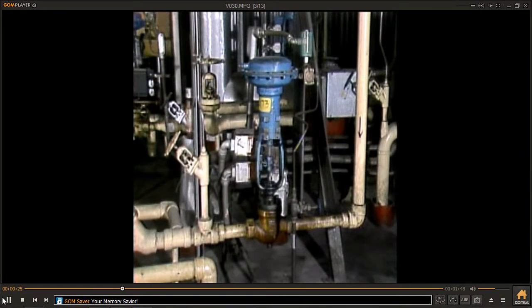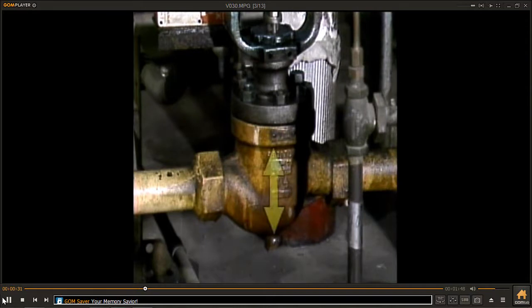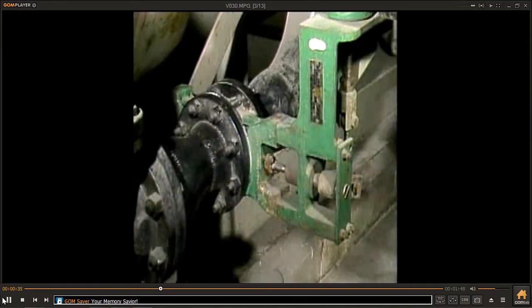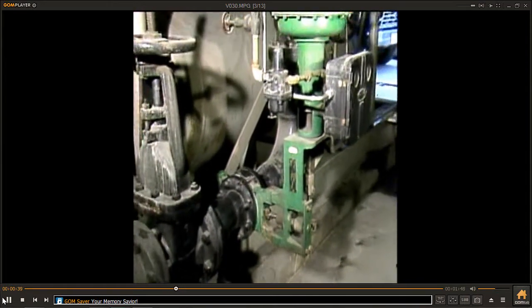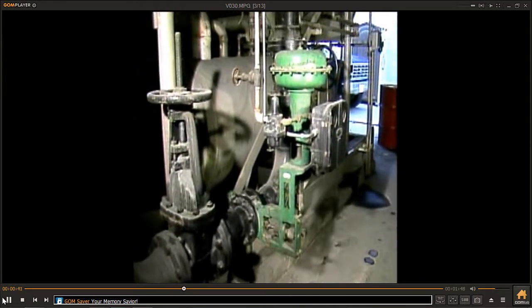Control valves work in basically the same way as manually operated valves. Control valves can be either linear, that is, the stem moves the valve disc up and down, as in globe valves, or they can be rotary, which means that they're positioned by rotation. Butterfly valves, which open or close with a 90-degree turn, are examples of rotary control valves.